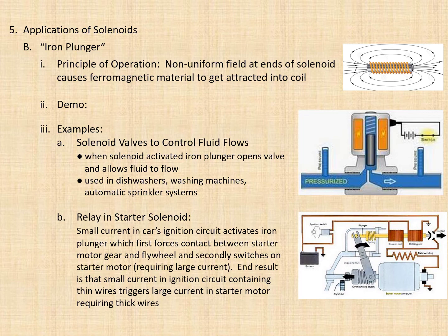So you may have noticed at some point that if the starter solenoid receives insufficient power from the battery, you might end up with a very rapid clicking sound in your car. If the solenoid doesn't receive sufficient power from the battery, because the battery's bad or because you've got a bad contact, the solenoid doesn't fully draw that iron plunger into position.